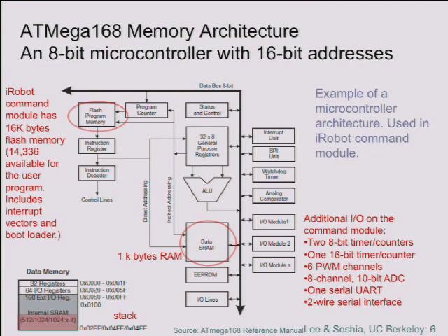So if you call a procedure and your stack pointer is already in here, you push your return address onto the stack. Your program will happily write the return address to an external I/O register. When it comes back to that, if it ever comes back to that, which it probably won't, it will get the return address from this external I/O register, which doesn't exist, and start executing code at this address that who knows what it is, right? You get chaos very quickly, okay? So you have to pay attention to what's going on in the processor in this case. You've got to pay attention to the depth of your stack.